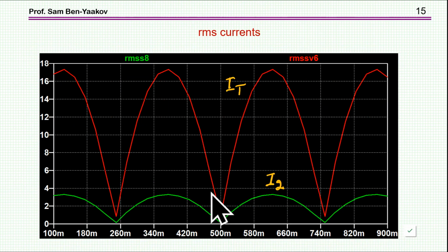And here is another look using the so-called performance analysis. Now this axis is the duty cycle. Okay, so this is like 0.74 duty cycle. I'm seeing here the RMS values of the ripple. This is the ripple at the secondary, and as we understand now, at the points of 0.25, it is exactly filling the period.